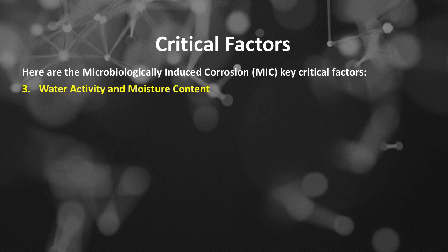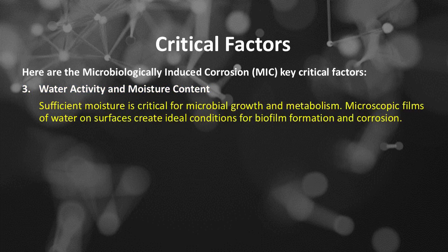Number 3 of the microbiologically induced corrosion, or MIC, key critical factors is water activity and moisture content. Sufficient moisture is critical for microbial growth and metabolism. Microscopic films of water on surfaces create ideal conditions for biofilm formation and corrosion.